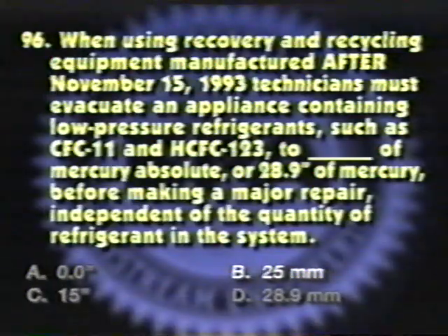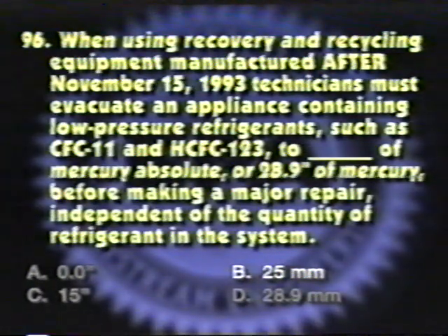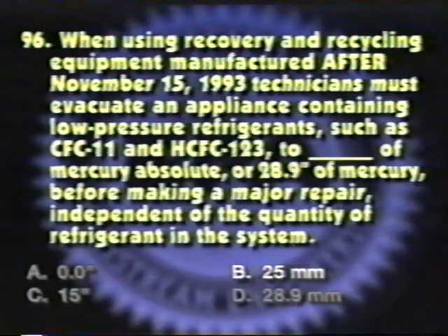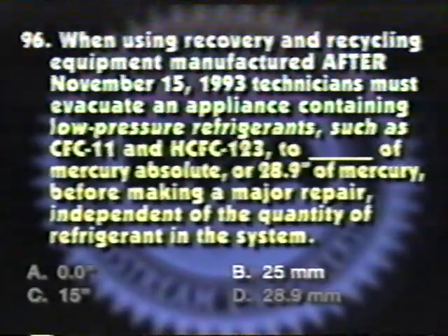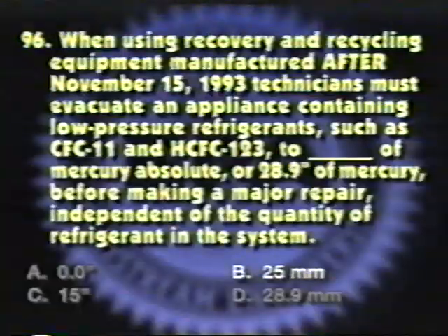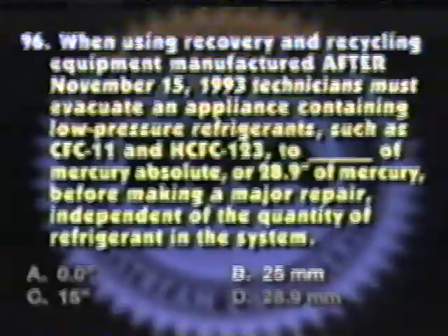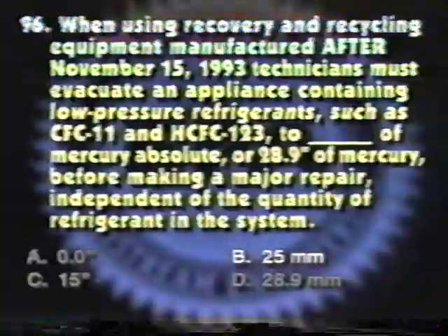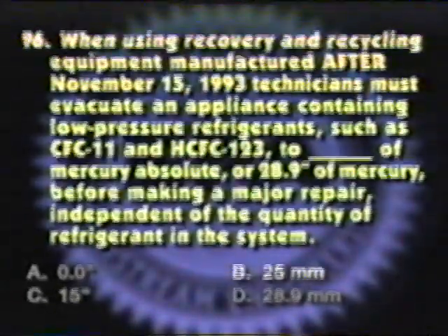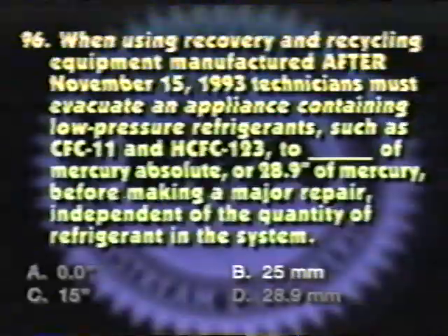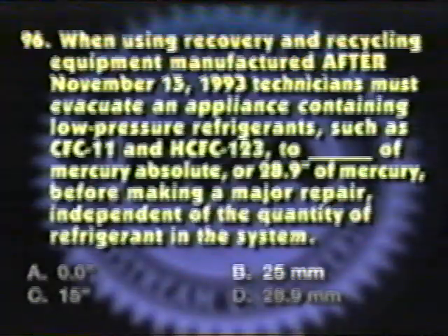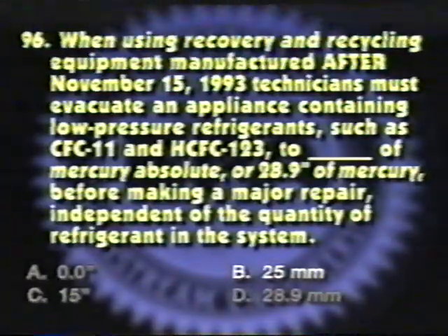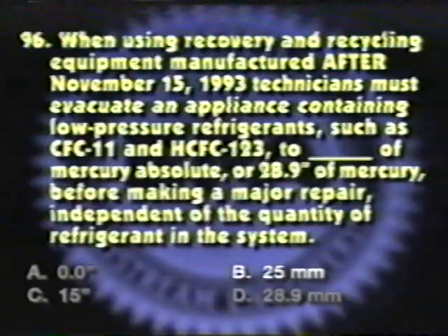The answer is B. When using recovery and recycling equipment manufactured after November 15, 1993, technicians must evacuate an appliance containing low-pressure refrigerants such as CFC-11 and HCFC-123 to 25 millimeters of mercury absolute, more commonly referred to as 28.9 inches of mercury, before making a major repair, independent of the quantity of refrigerant in the system.